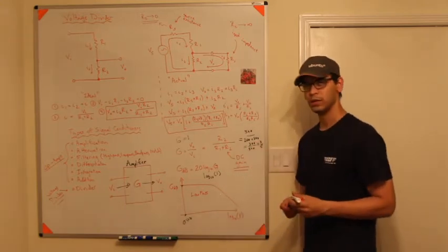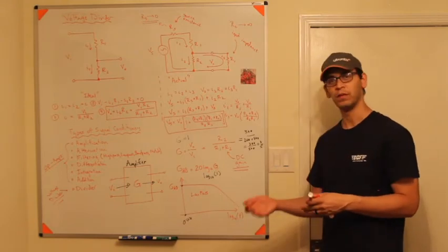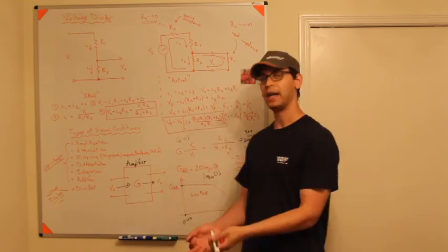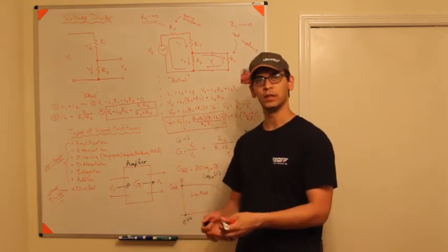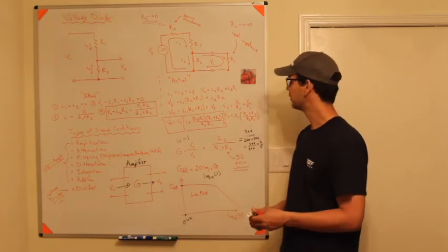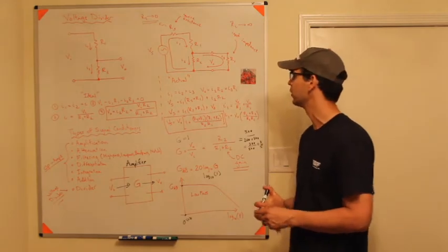So that means that you would multiply your voltage by 3/5 to get your output voltage. You have essentially divided your voltage signal and reduced it. You've attenuated it at that DC gain, right? And I say DC gain because I'm assuming this voltage source is direct current.